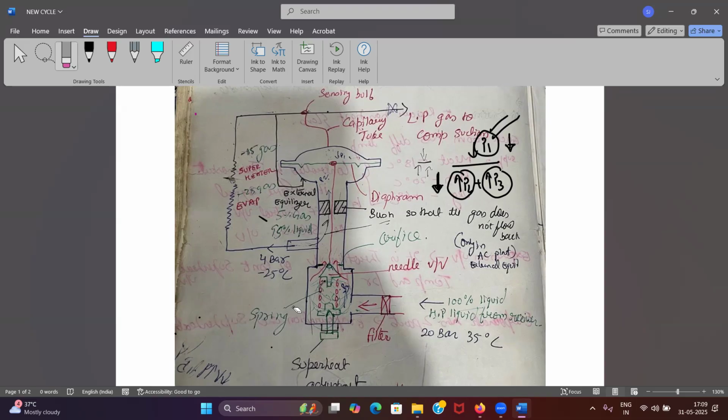Okay sir, so accordingly at the evaporator outlet, relatively it will be... If it is confusing, remember this much: P1 should be greater than P2 plus P3. If you are increasing P3, P1 has to correspondingly increase in order to open the valve. That means I need more temperature over here, so more heat exchange should happen over here for the superheat. Now you understood? Understood, understood. Fine.